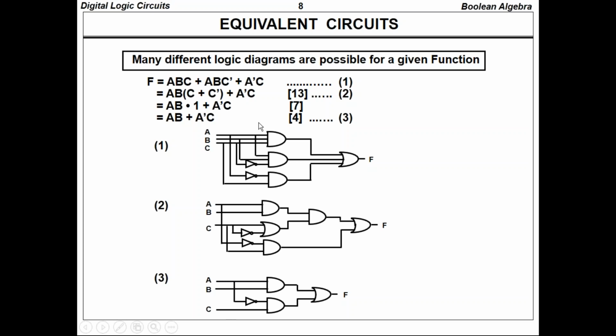So like this we are simplifying, that means we are getting only one AND gate, and here one AND gate, and here one NOT gate, plus here one OR gate. So total simplification is only 3 steps. So you have simplified that expression, and it contains only 4 logic gates. Instead, using the same expression I would get more than 4 or 6 logic gates. So that's why we are using Boolean algebra to simplify our expression.